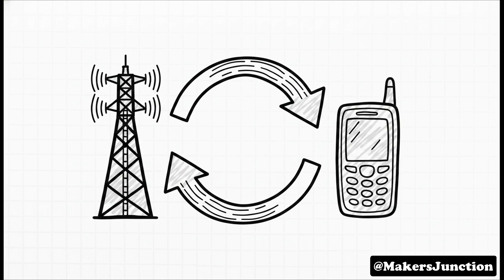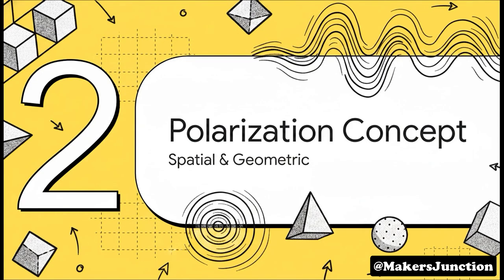Just to quickly set the boundaries for our explainer today, the definitions in this standard assume that the antenna is a passive, linear, and reciprocal device. Now, reciprocal is a fantastic word here. It basically means that if a definition talks about the antenna transmitting, well, its use in a receiving situation is perfectly implied too. The physics work beautifully in both directions. It's a two-way street.